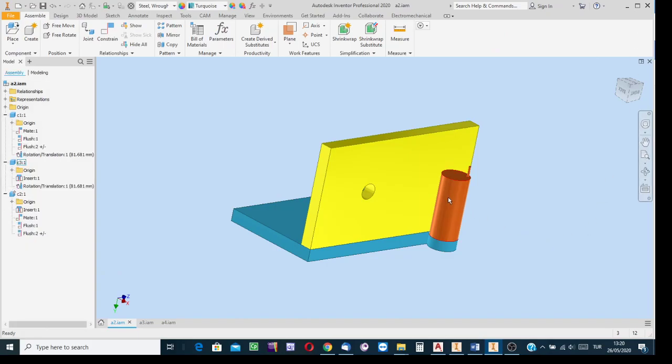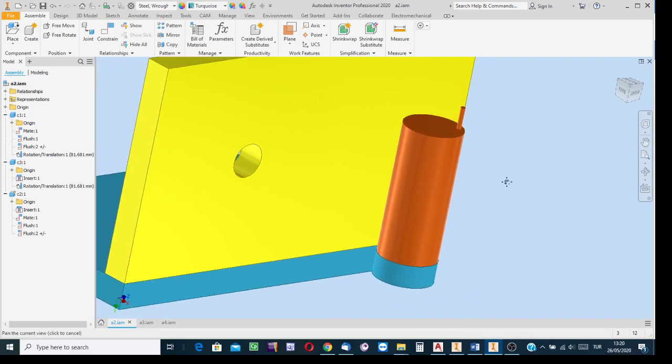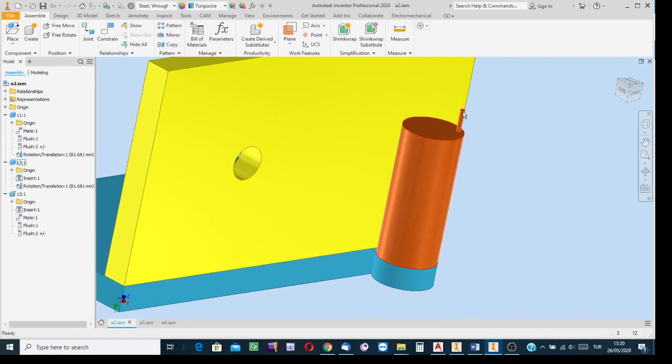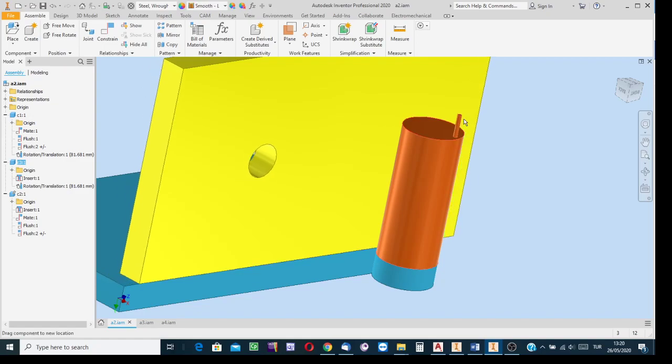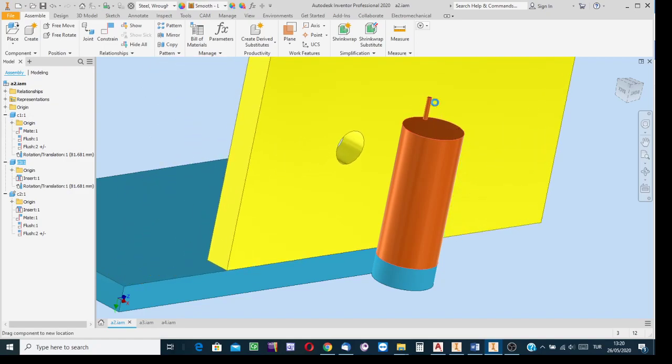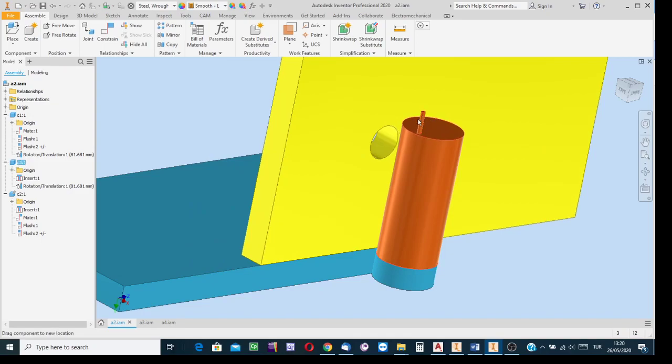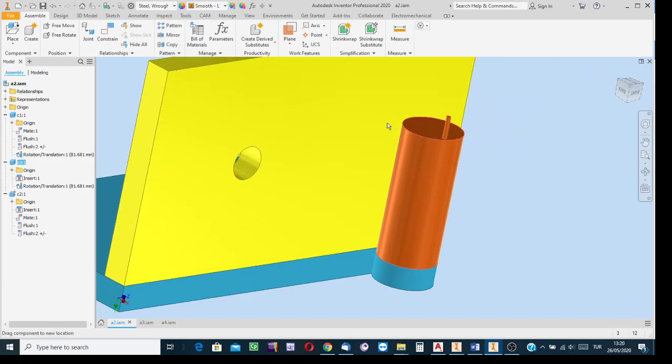And then, yes, the brownish one is to rotate. Okay, as suspended by the bearing, supported by the bearing. How? To make it distinguishable, I added such a cylindrical extension. You see, I am rotating the brownish one, and while it is rotating, the yellowish one is reciprocating. Yes, because there is a motion type constraint. Before talking about this motion type constraint, well, understand the insertion constraint.